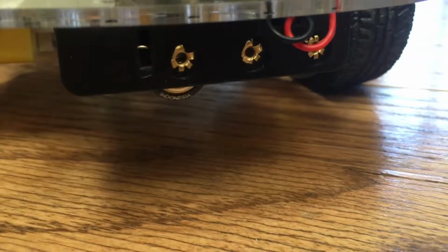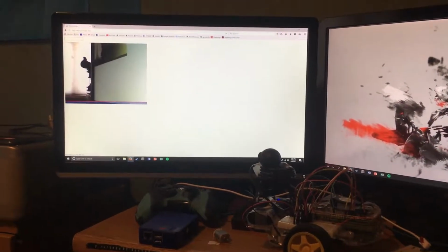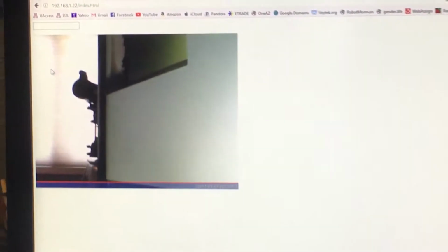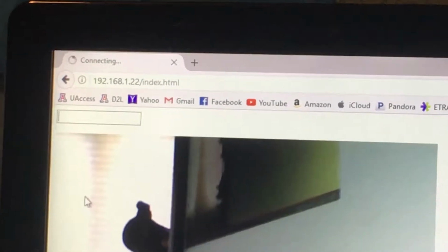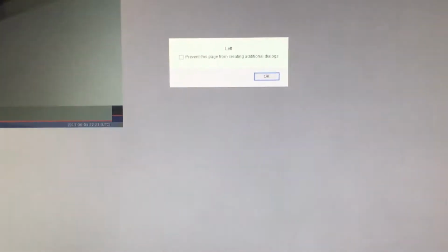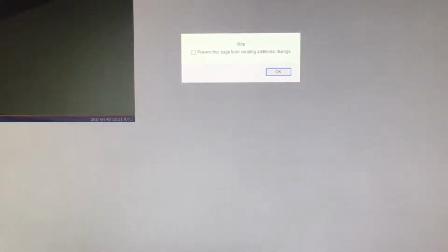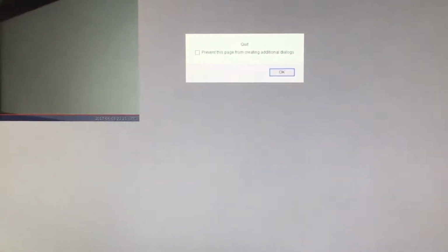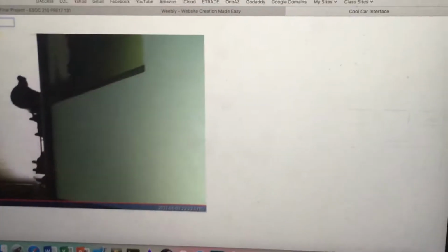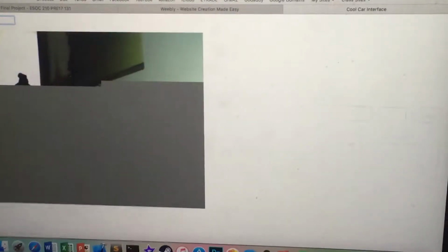The second output is the image generated by the webcam. This image is sent via the Raspberry Pi's web server, which is told to refresh every 2 seconds to retrieve the updated image. The Wi-Fi interface is made possible by the third-party Apache web server that turns the connection to a Linux computer into a personalized website. The camera interface is done through a third-party software called FS Webcam and gives the user control of their webcam through a command line interface. Finally, keyboard inputs are made possible by a Stack Overflow user who solved Python's inability to take immediate inputs through some input stream manipulation.